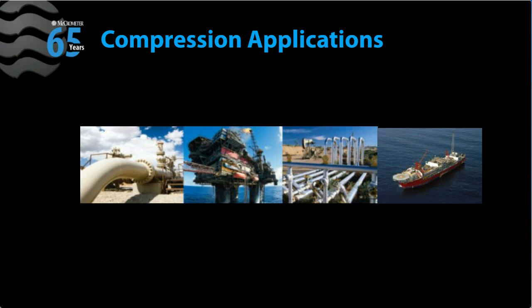So how does this V-Cone meter work? It's got two differential pressure taps, and one measures the high pressure, which is the gauge pressure of the line. And the cone, because it's welded in, conditions the flow area in order to generate a differential pressure, which is measured out of the low pressure port. And this differential pressure will be a direct measurement of the volumetric flow inside of the line.